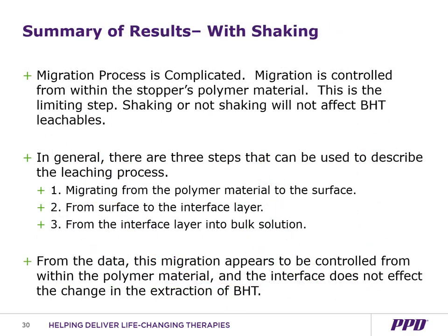So to summarize, the migration process is very complicated. There are a lot of factors that go into compounds migrating from polymer materials. From the data shown today, migration is controlled from within the stopper's polymer material. This is the limiting step. Shaking or no shaking will not affect leachables significantly.